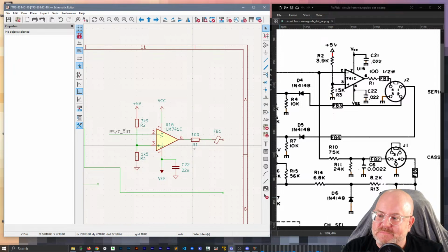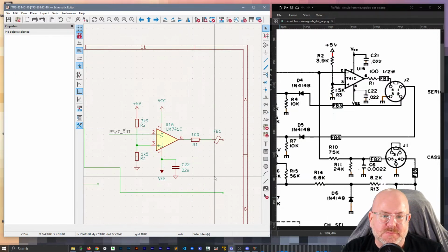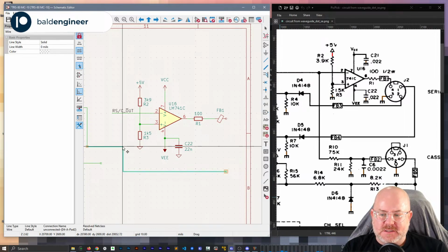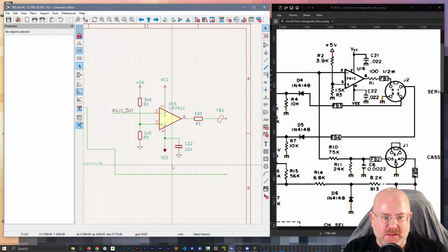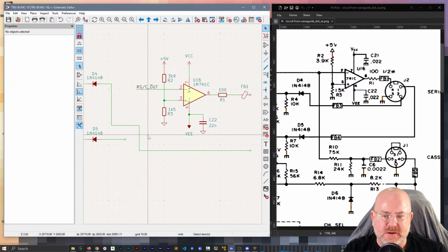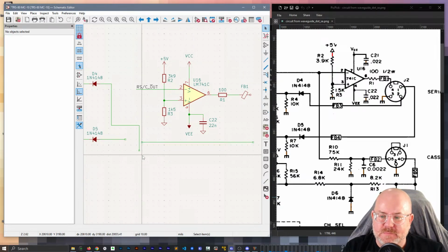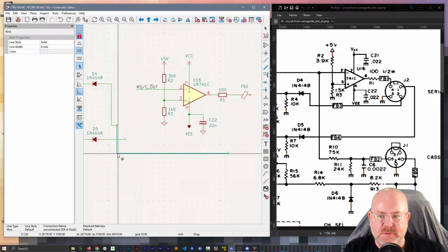Yeah, I feel like everything related to zones, everybody blames on bugs. And I've been bitten by that myself, where I'm like, oh, DRC is wrong. It just doesn't know what it's talking about. And it was like I had two zones overlapping each other. In fact, DRC was telling me that I had two zones overlapping each other, and I was telling it that it was wrong. So I learned that lesson. It turns out that's one of those lessons you only need to learn one time, and then it doesn't happen again.